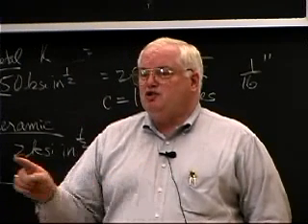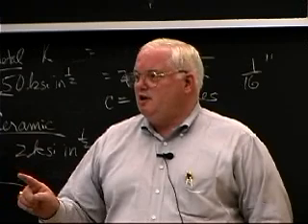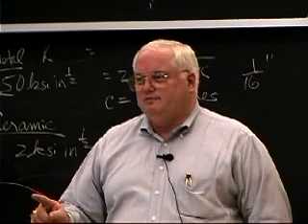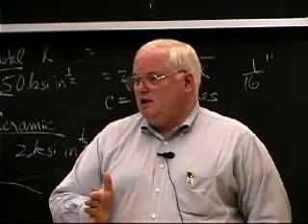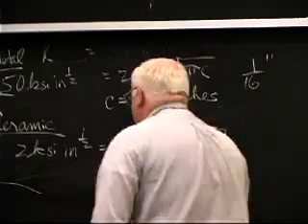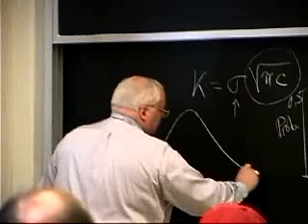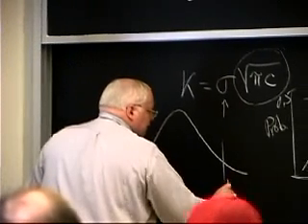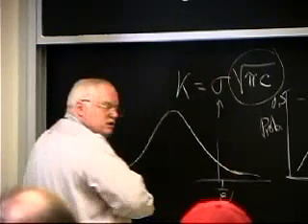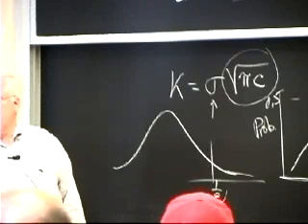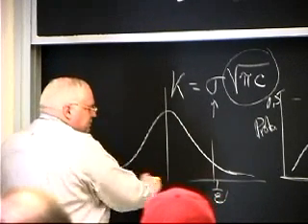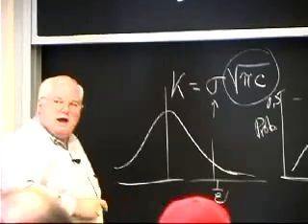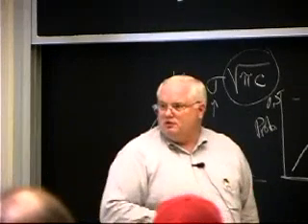If you now assume that your structure has no flaws bigger than 1/8 of an inch, you're kidding yourself. Okay? But as long as I don't have too many flaws of 1/8 of an inch, I'm dealing with the fact that I know things are going to be a Gaussian distribution. If I only have a few flaws that are 1/8 of an inch, how many really big flaws am I going to have? None, essentially. If instead the population of 1/8 inch flaws is down here, I could have some big flaws that could be critical to the structure.